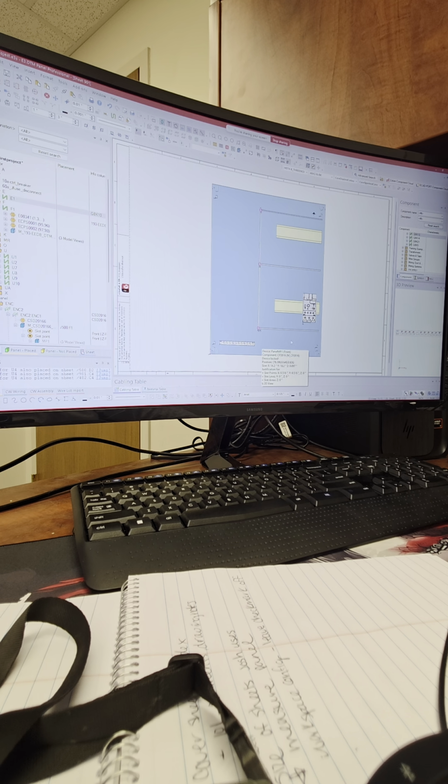Somewhere in the bottom, etc. But the same thing with all these other parts, these paths that you're setting up. Keep in mind, if your wires are not showing going from one part to the other, you need the ducts in between. If the parts are too far apart, let's say the VFD and the ground bar, the wire will not automatically route between the two. So you will either have to bring the parts closer together, or include the duct in between them, even duct as we have it here, so there's a path for the wires to go and chase each other down.